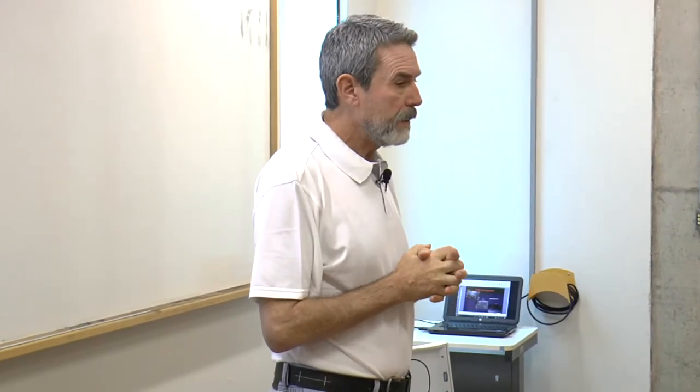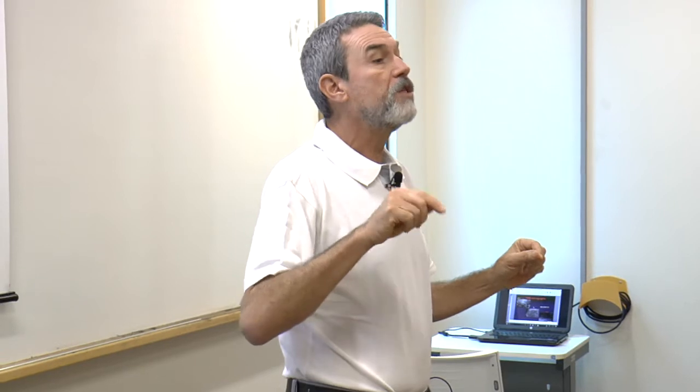In summary, there are different uses of this liquid-liquid or glass-in-glass phase separation phenomenon. We are going to take a look today at the thermodynamics and kinetics of this process, and then of its role or influence on crystal nucleation, because the next class will be on crystal nucleation.